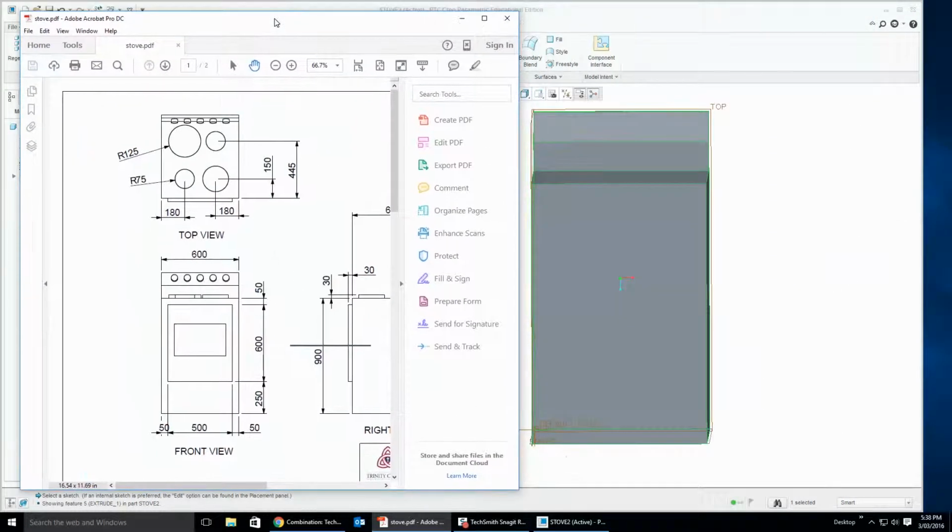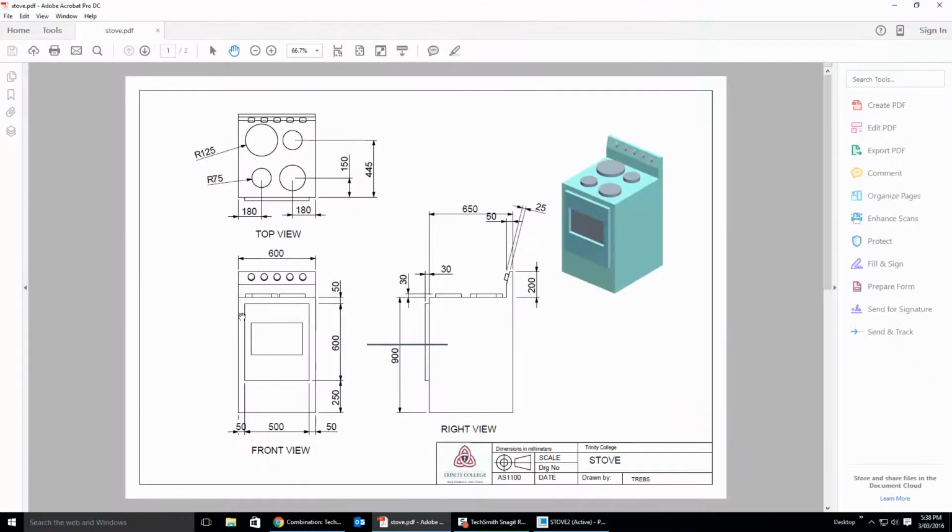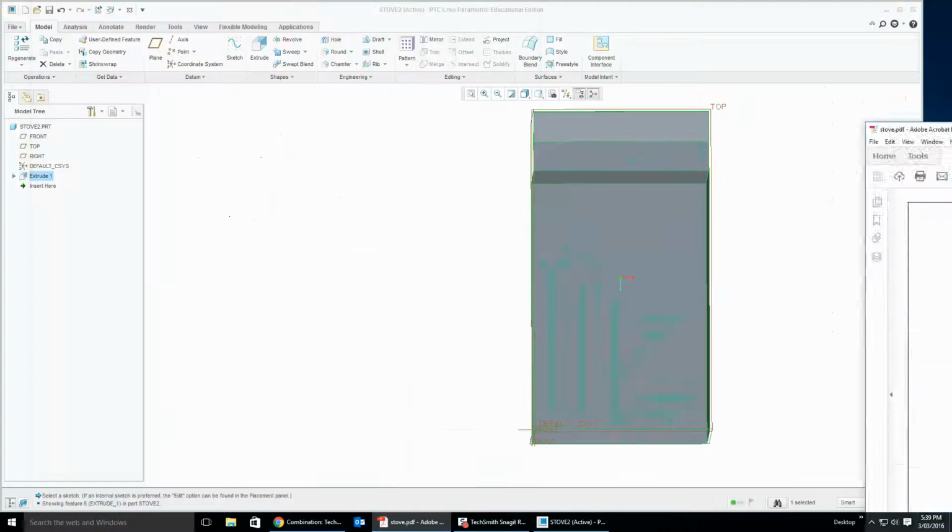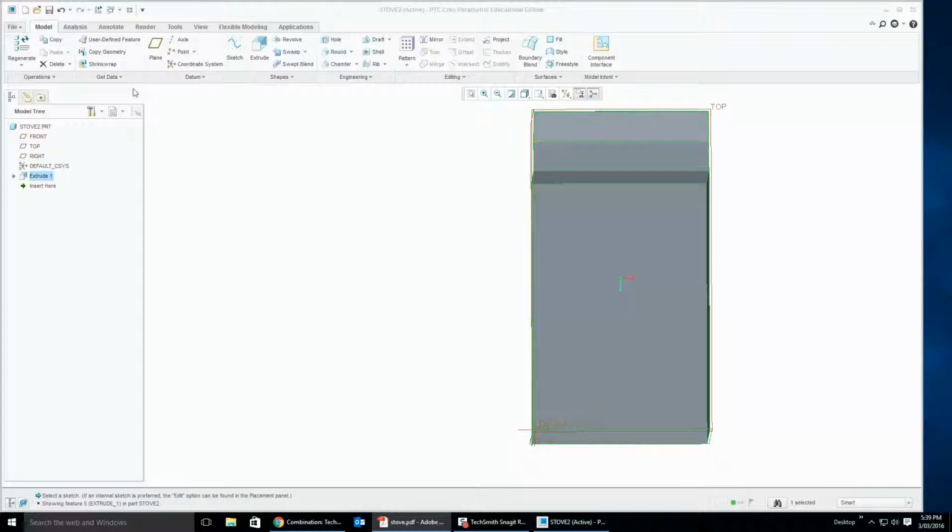We're now going to move on to some of the front parts, which is a bit trickier. We might start with the round dials, which is going to go across that edge. Sorry, before I do that, looking at those there, we know that that has a height or an extrude depth of 25. What we don't have here, if you look very closely, is our diameter or our radius of those circles. So we're going to take a little bit of a guess there to draw them. You can make those up as you go through. It's just not indicated on the drawing, and I'll give you a measurement that I want you to key in after I've worked it out.